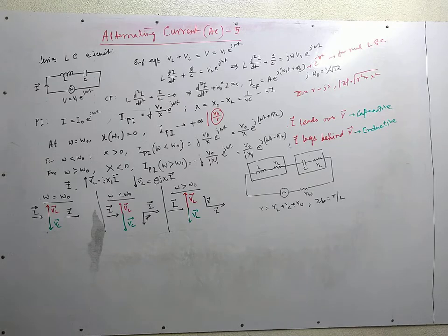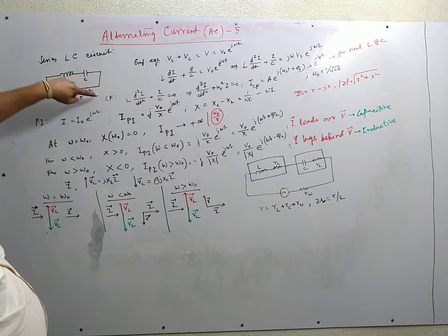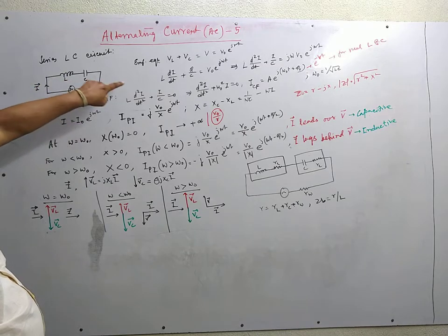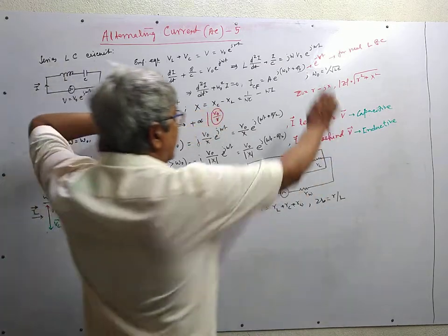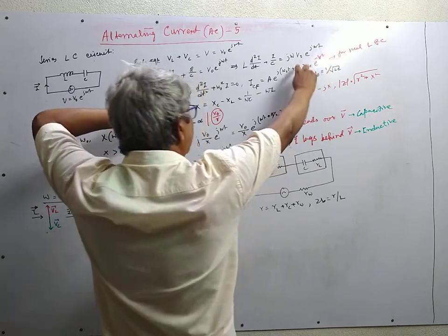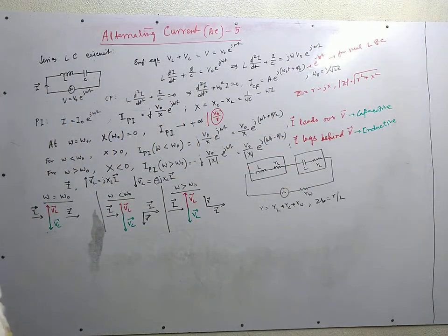Otherwise, had it been an undamped motion, that is no resistance, then the total solution would be the combination of CF and PI, and if both of them are sinusoidal, the resultant will be the superposition of two sinusoidal oscillations, which will form a beat.